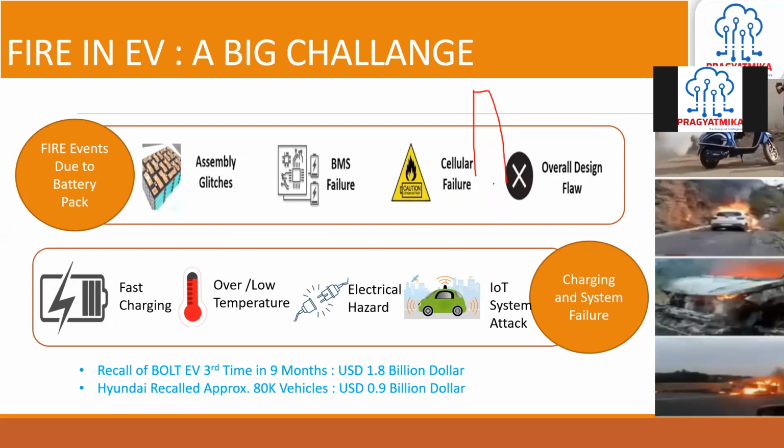If this is one electrode, behind this there is another electrode, and in between there is a separator. Now there was a certain rolling on the corners of the separator in a few of the cells, and this absence of the separator on those corners was creating an issue of short circuiting between these two electrodes.